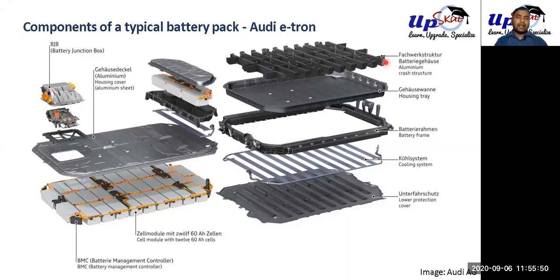It also acts as a housing for the batteries, right? These are our batteries. They will sit on top of it, so these will slide right into these slots, all of these batteries. Here you can see lots of wiring and connections. Some of these connections are very strong, thick copper pieces. Okay, these are called bus bars, connecting each and every battery. A similar thing is visible on lead acid batteries also. So this is how we do the series and parallel connections.